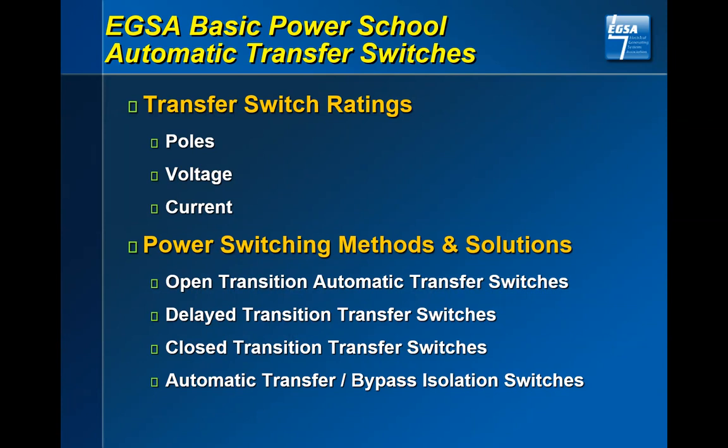However, if you're carrying the neutral through that transfer switch, it may need to also be switched. We will cover that, and therefore you have a 4-pole transfer switch. When you're looking typically at single phase, that typically is a 2-pole transfer switch, typically 240 volt here in the United States. I understand this audience here is Hawaii and basically the West Coast and such.